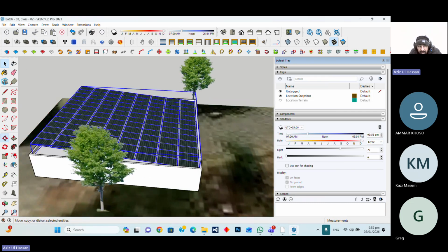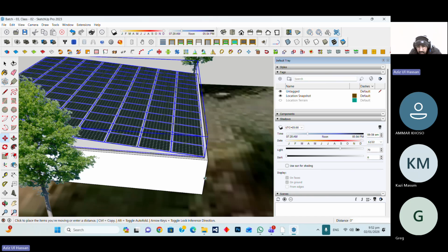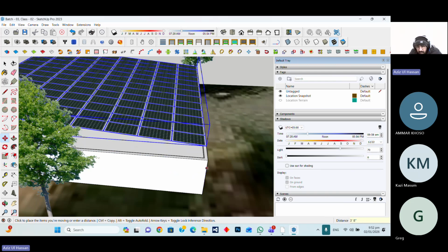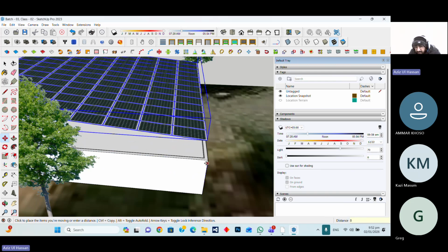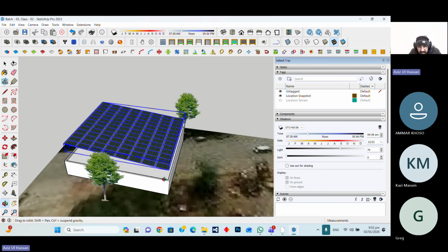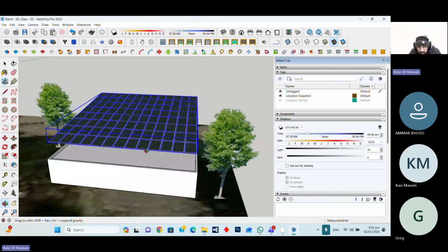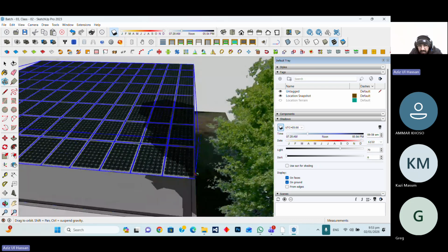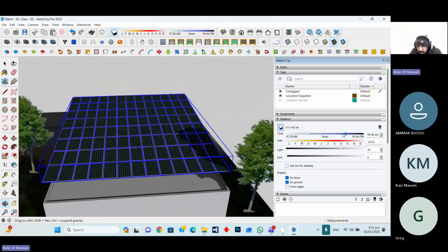Now we give the height from the front elevation, 8 feet height from the front. Now you can see what the effect of that shadow is. When you make this type of structure, you have to make the structure as per the girder and other things. Now you can see that it is also creating a shadow on the PV modules at 10, like 10, 9.